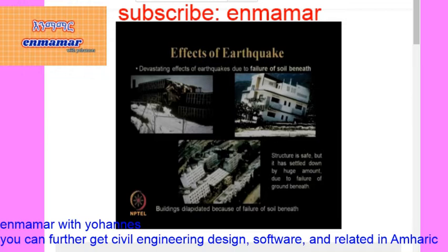This type of problem is related to our geotechnical earthquake engineering, because here the superstructure was designed properly, but not the foundation, considering the behavior of the soil during the earthquake. This is another picture of buildings which are dilapidated because of failure of the soil beneath. You can see over here there are a few rows of houses standing properly, but the similar houses in the row just behind have collapsed completely, or tilted partially. These are because of the local regional soil, which is very important to characterize during the earthquake process.